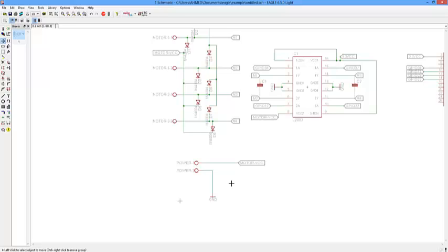Generally you will not have this problem with the Raspberry Pi, but this is an extra advice for people who are using microcontrollers like Arduino or PIC or AVR or STM. They connect everything and it does not work for a simple reason, my friend. These motors are still spiking your VCC and ground. So that nice spike goes into your microcontroller and restarts it, or in other cases it kills it.